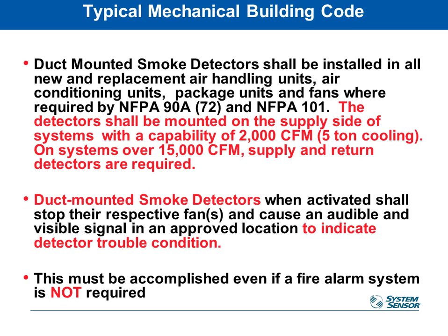Once you get up to about 15,000 CFM, then you are required to put a smoke detector in both the supply and the return duct. So you will have to use two of them on larger air handlers.